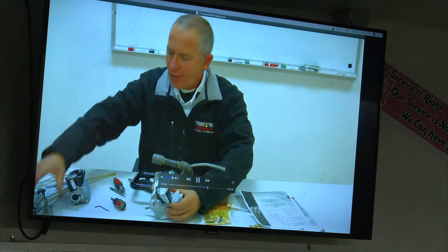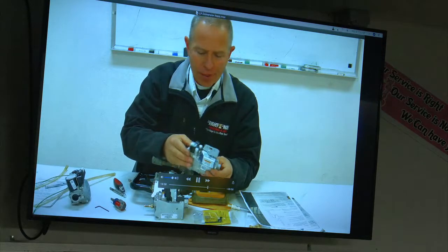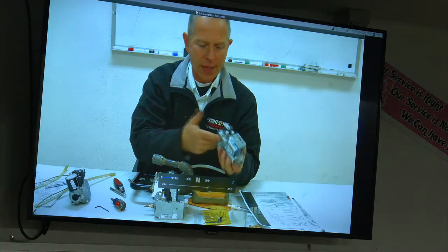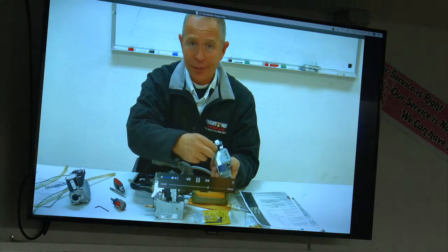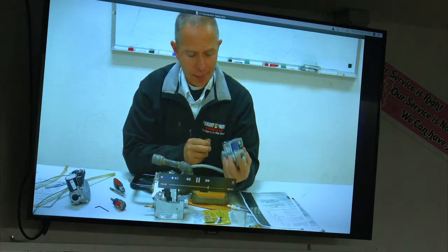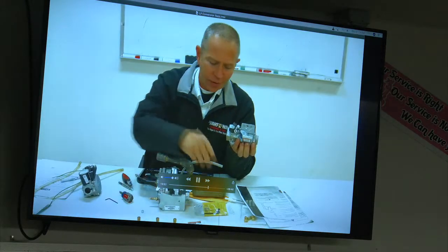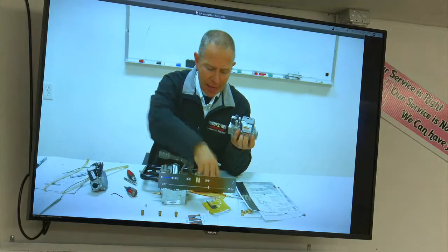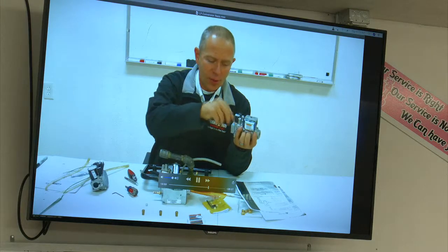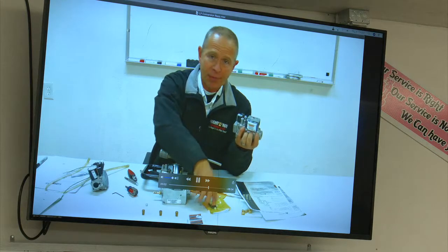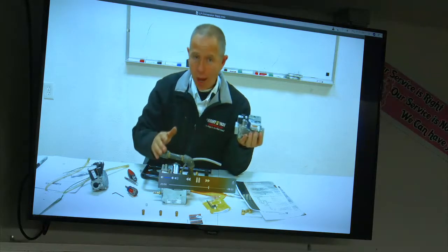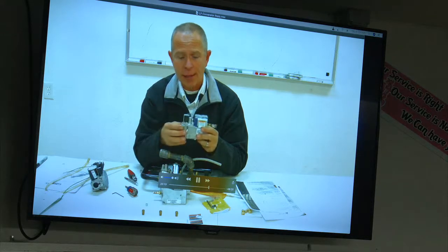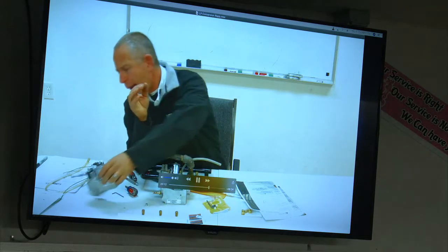Okay? So this is a Honeywell valve. Same principles. It has the 3/4 or the 1/4 inch barbs that go in it. It has a little bit different screw setup. This actually uses a star Torx, but they provide the star Torx. So all you do is loosen that out. You're going to use the new set screws, the new springs, and caps on this particular unit. Same process of the incoming pressure, same process of setting up the 2-stage valve on that part there.